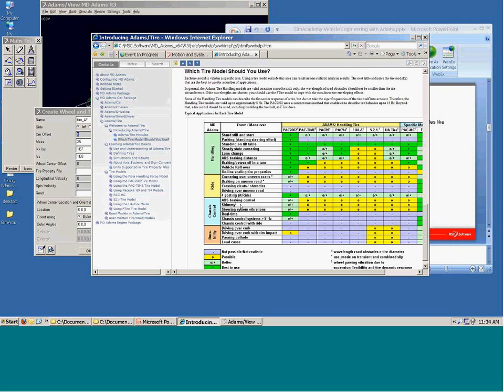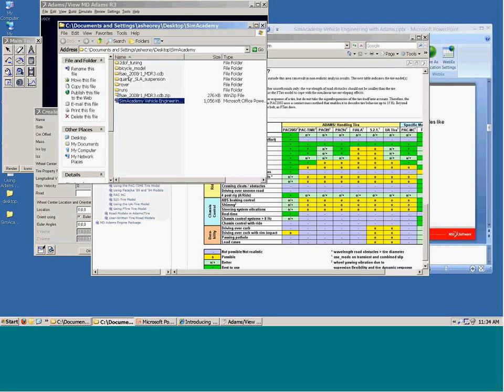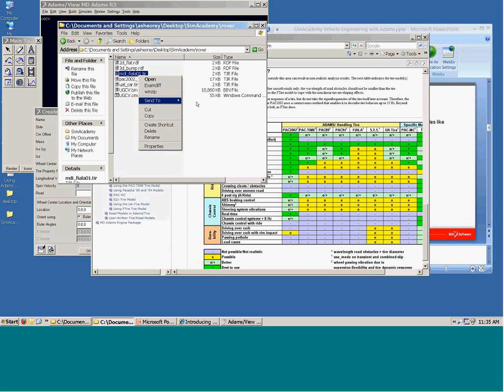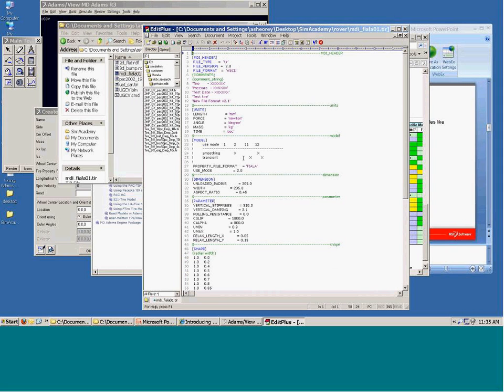What does this mean? Many times what we have seen is that getting tire data is difficult. So you can start off with a simple formulation called a PLR tire. Again, it has vertical stiffness, vertical damping, and then slip values and so on.